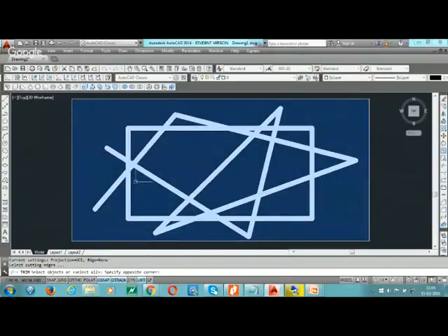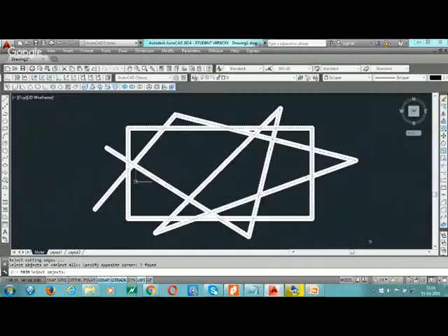So I will make a window. So all these objects are now selected. Now it is asking select any other object. Is any left? No. So I will press enter. Right. Now it is asking me the options: trim, fence, crossing, project, edge, erase, undo. So these are all the default methods. Trim.